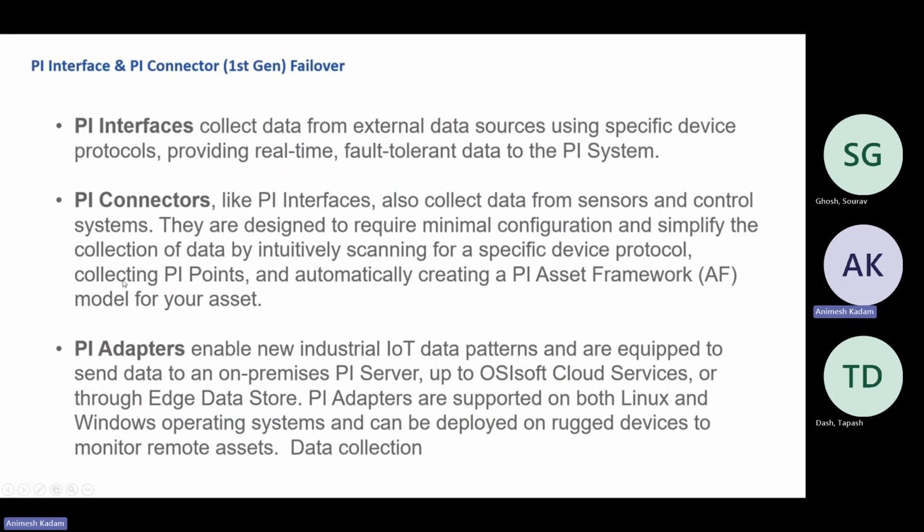But the only plus point is it pulls the hierarchy from your DCS, it pulls the tag configuration from your DCS and OPC and creates it automatically in the PI server. In the case of adapters, there are different types of adapters which collect data from different types of devices like IoT devices, sensors, or cloud devices.